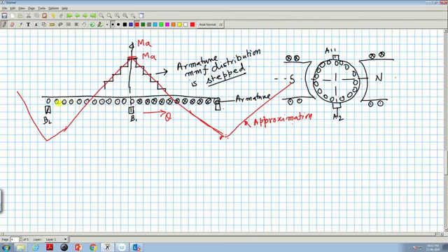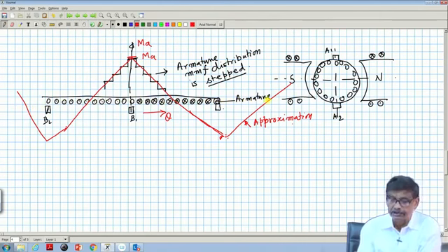Between the brushes, current polarities are the same, dot on this side and cross on this side. These are armature conductors, and they will carry current. I know for a single coil how to sketch the MMF distribution, which will be rectangular, plus and minus.